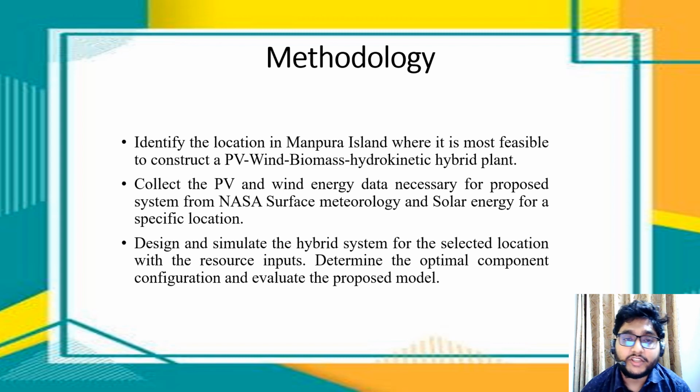Methodology. Identify the location in Manpura Island where it is most feasible to construct a PV, wind, biomass, hydrokinetic hybrid power plant. Collect the PV and wind energy data necessary for the proposed system from NASA Surface Meteorology and Solar Energy for a specific location. Design and simulate the hybrid system for the selected location with the resource inputs. Determine the optimal component configuration and evaluate the proposed model.